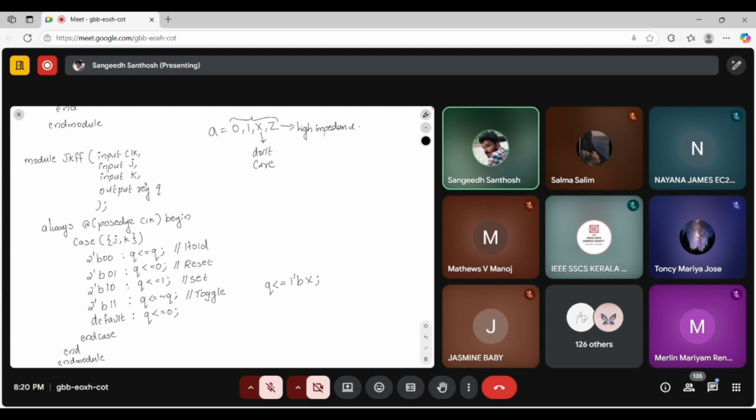Okay, so in all these flip-flops, I have not used a reset condition. This reset condition you can also include in the input signal, and it can be either synchronous to the clock or asynchronous to the clock. Synchronous and asynchronous reset we will be discussing more when we move towards FIFO and FSM. That we will deal with in the next class.